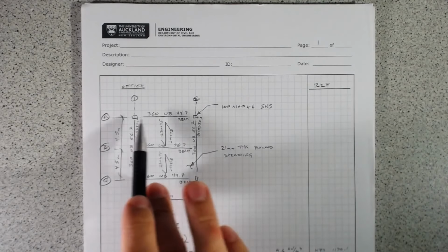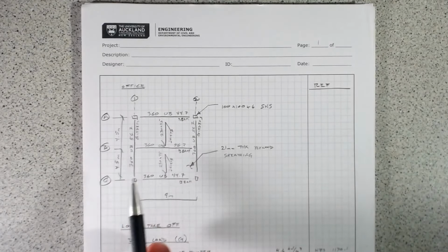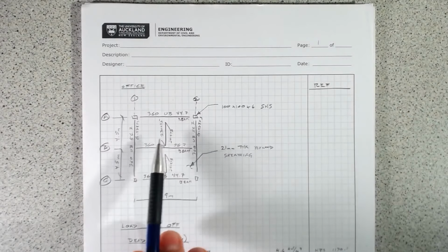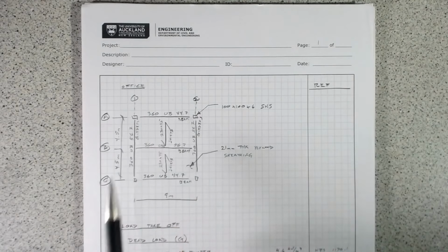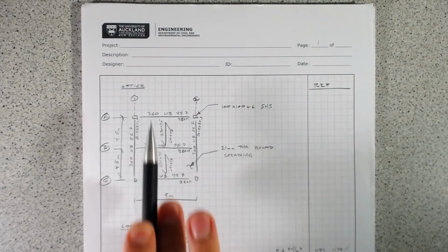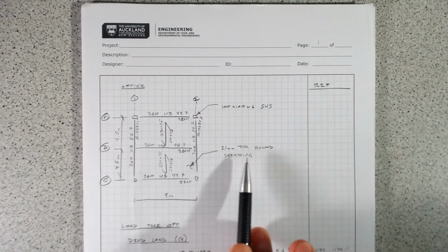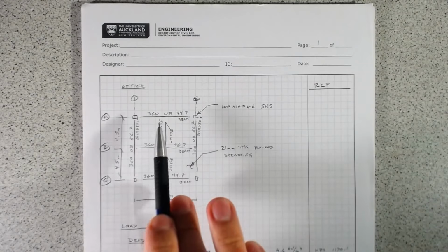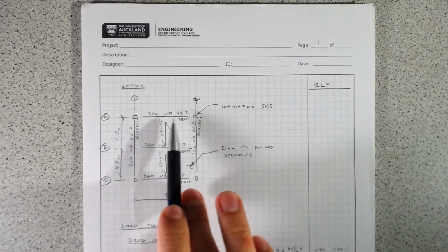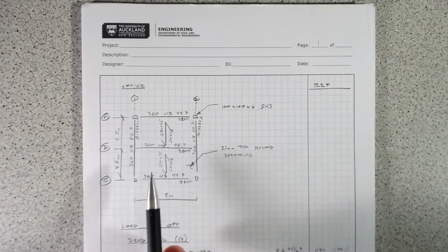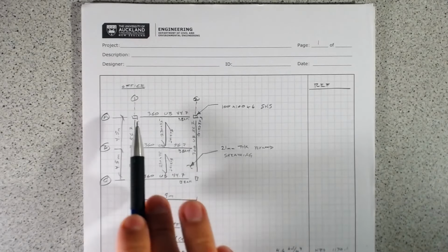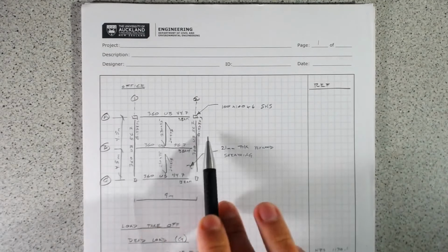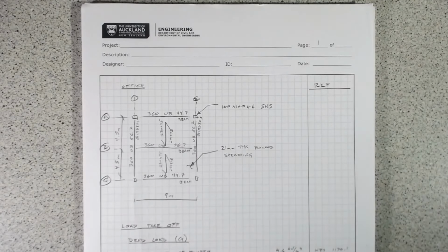The secondary beams are 360 UBs by 44.7, so universal beams, so steel beams there. We have joists, which are 230 by 45, spanning in this direction, and there's a 21 millimeter thick plywood sheathing over the entire area. So the two external secondary beams are these 360 UB by 44.7. The internal secondary beam and the two girders, or if you like primary beams, all three of these are 360 UBs by 56.7.